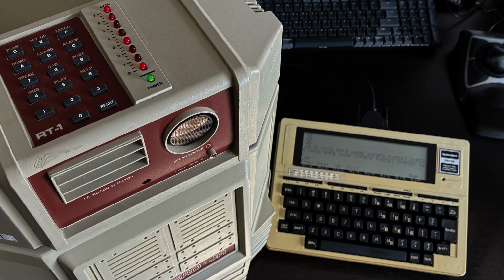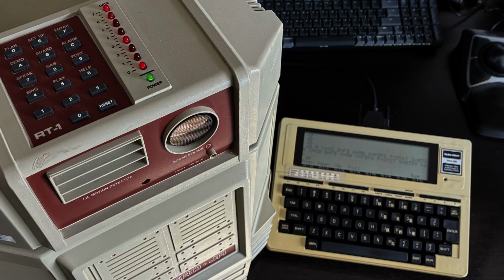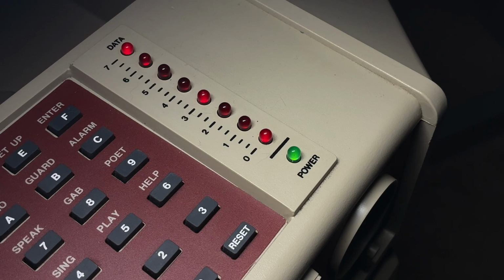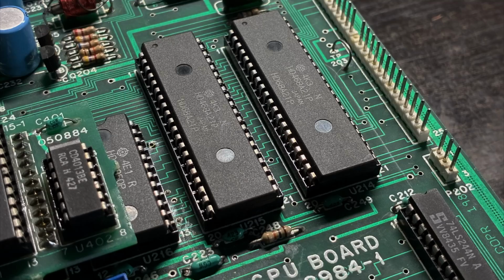This week, let's keep the ball rolling and look at the Junior's other major form of communication, its keypad LEDs. We've seen the set of 8 red LEDs blinking wildly every time the robot speaks, but they're not just a blink and light display. They can be harnessed for our own purposes as well. The LEDs are driven by U215, PIA number 2, and by writing values to the PIA registers, we can output binary patterns to the display.